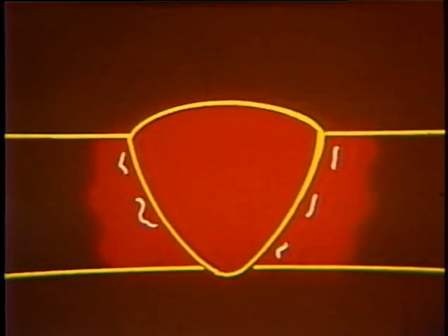Heat-affected zone cracks, also called underbead cracks, generally occur during the cooling cycle after solidification of the weld and normally do not extend to the surface of the weldment. They are usually short in nature, but can connect with others to become continuous cracks. Heat-affected zone cracks can also occur after the part is placed in service because of embrittlement of the weld and the heat-affected zone.